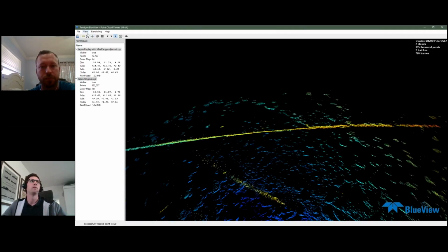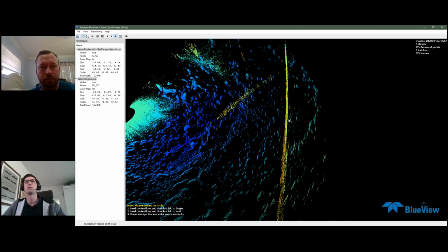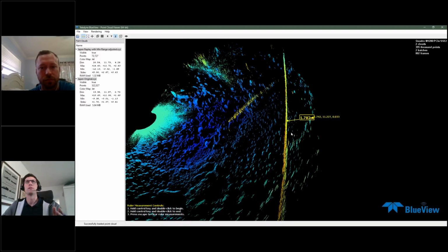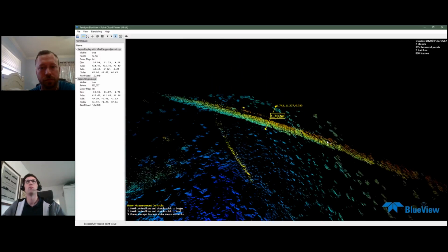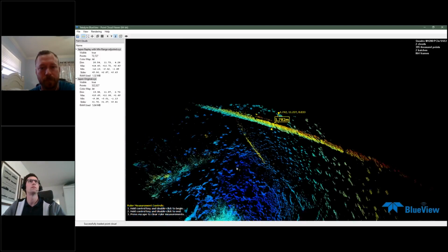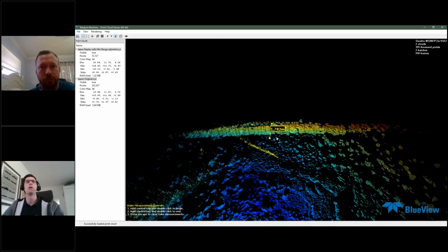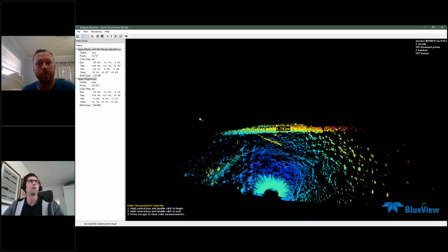In fact, in Blueview, we can even do a measurement here of how deep the scour goes. Let's say there. So again, ballpark measurement, but about 1 3/4 meters cut on the scour, and that's enough for the end user to basically go in. Okay, we need to repair the wall. We need to send a diver maybe to further inspect if possible. In this case, it was hard for a diver just given how cold the water was, how fast the river was moving. So this gives us a very clear picture of what's going on.